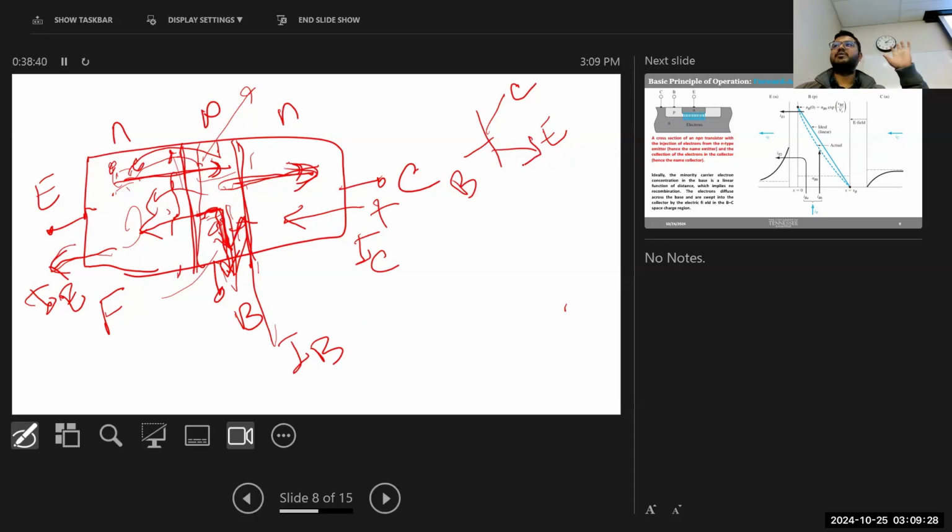In the very first slide, you remember that, right? For NPN, we had this outward arrow. And if we do the same thing, the current flow and electron flow for a PNP transistor, we will see that the direction of emitter current will actually be towards the inside of the device. That's why we had that inward directing arrow for PNP.